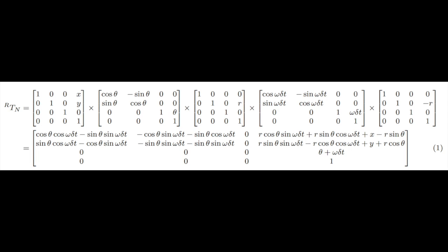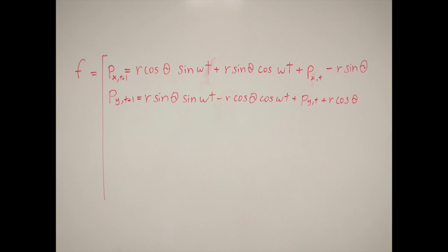We then need to apply transformations from the robot's base coordinate system to the coordinate system in which this model applies. The three values in the top right corner of our matrix are our result. They are respectively the robot's x position, y position, and orientation. After all that, we are finally ready to define our transition function f.